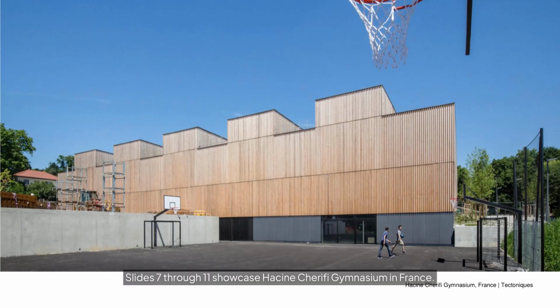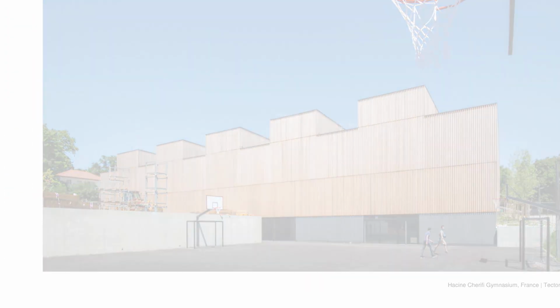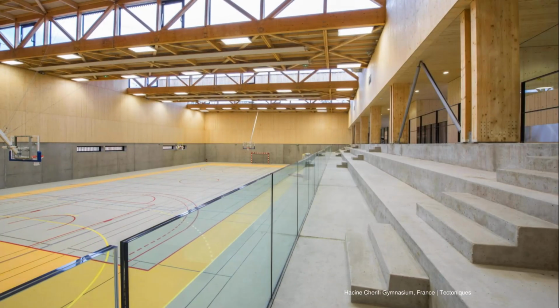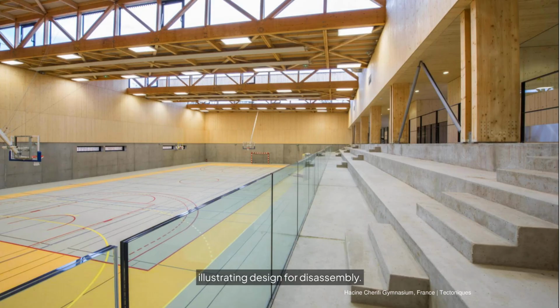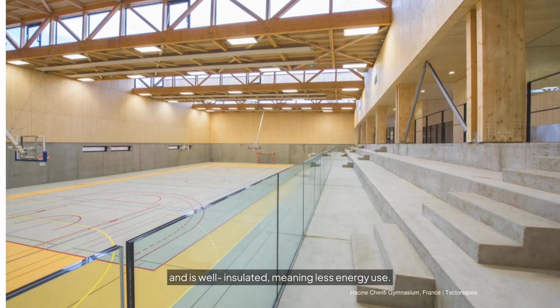Slides 7 through 11 showcase Hacine Cherifi Gymnasium in France. This modern gymnasium showcases regenerative design by using renewable materials like glue laminated timber and agri-waste insulation and minimizing waste. The glulam frames span 34 meters and are built in sections with bolted connections, illustrating design for disassembly. The column-free space meets the gymnasium's needs. The interior space is bright with clerestory windows and is well insulated, meaning less energy use.